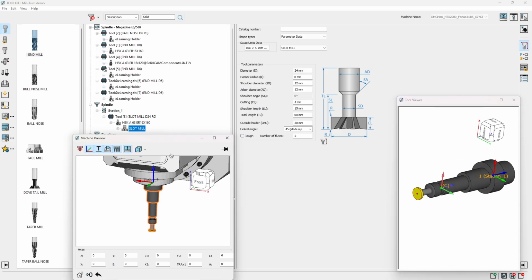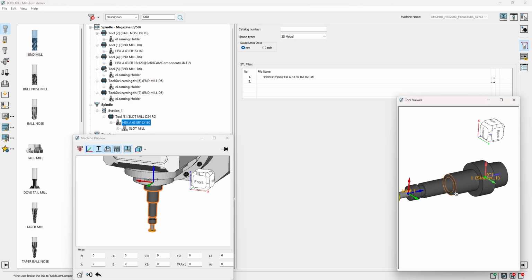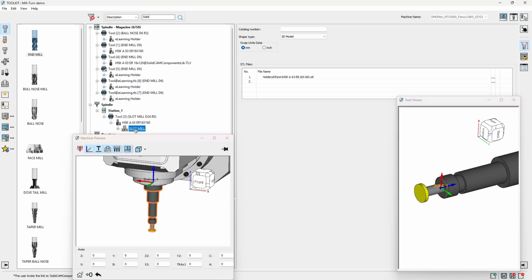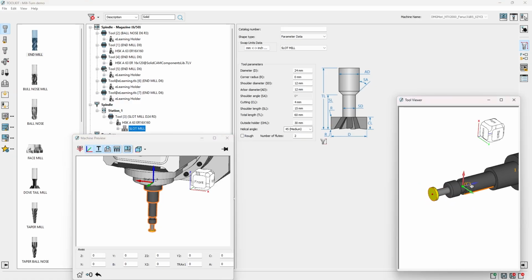While selecting each of the components here, you can see the coordinate system change. I'm going to click on the holder, and the same will be demonstrated. The coordinate system of the STL is located over here, while we also have our joint defined here with a joint name. Similarly, if I click on the cutter, I'm going to see only the coordinate system of that cutter. Right. How can we manipulate the locations of these cutters and these components in the assembly?